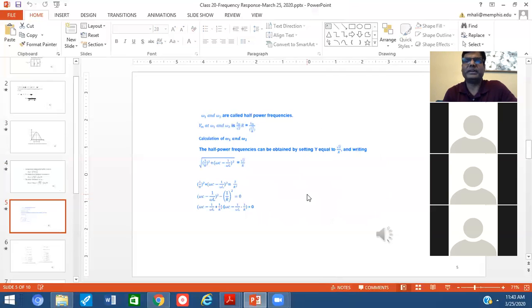So moving forward in the next slide, now our target is to calculate those two points, omega 1 and omega 2. As you can see, Vm at omega 1 and omega 2 is Im multiplied by R over root 2. This means Im over root 2 over R. It is the same meaning, but I'm writing it that way to show that root 2 over R is the admittance.